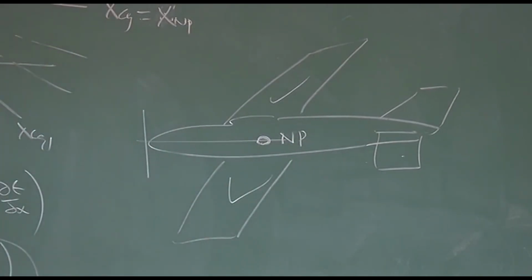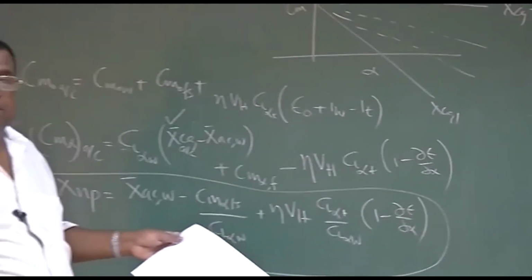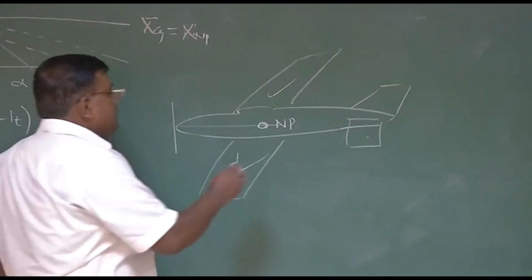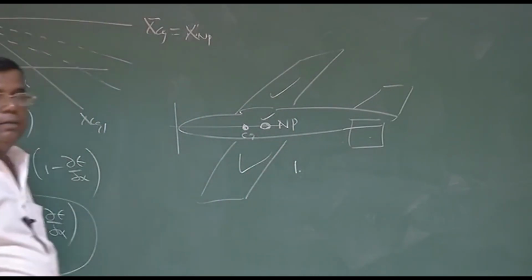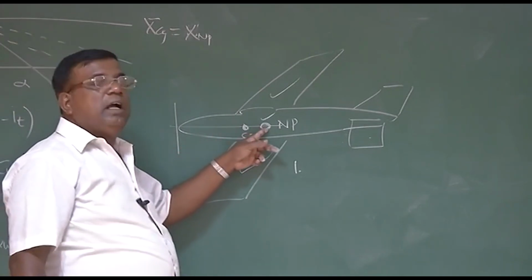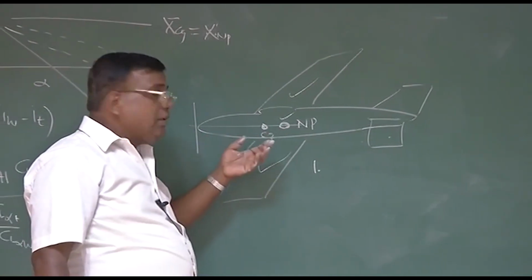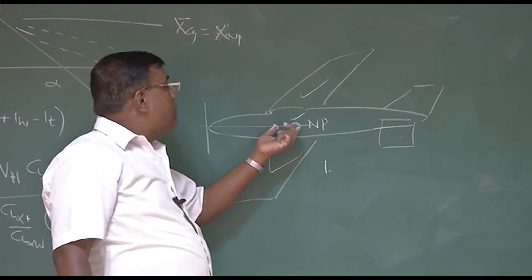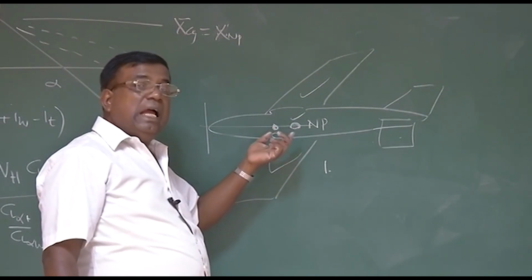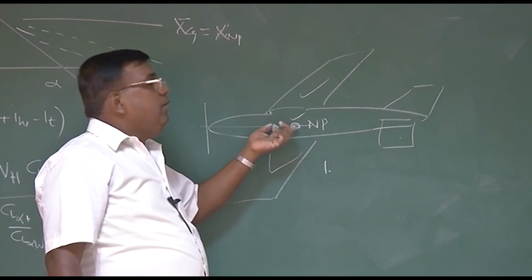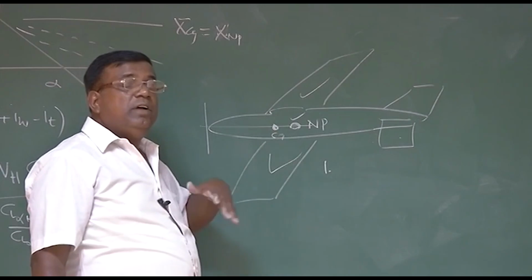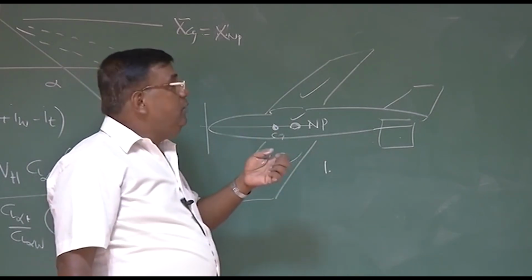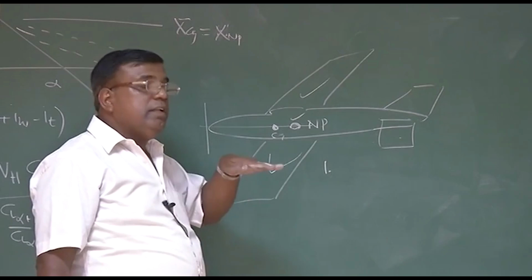Okay? What is the message to us? Message is, when you are doing a layout of your mass distribution, please ensure first that the CG of the whole airplane should not cross this. Because if the CG comes here, the aircraft will become neutrally stable. Second question comes, you should know a priori how much should be this separation. How much ahead you should be for your stability and control purpose, because you know if this separation is too high, it will be very highly statically stable. So you need to have large control force to control it from one CL to another CL.